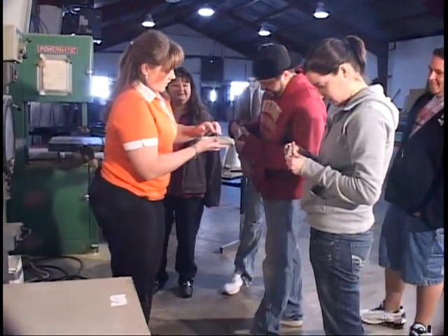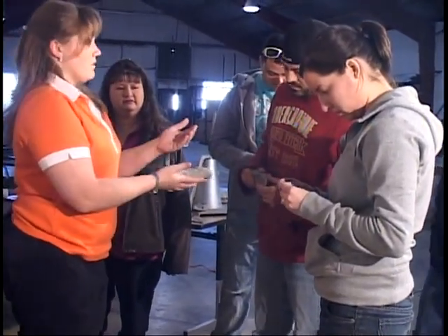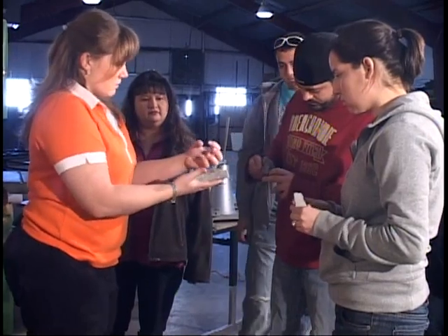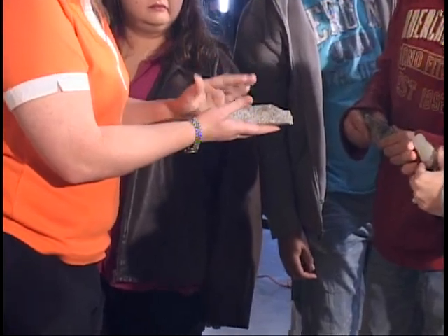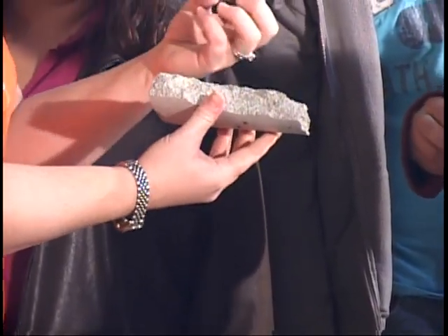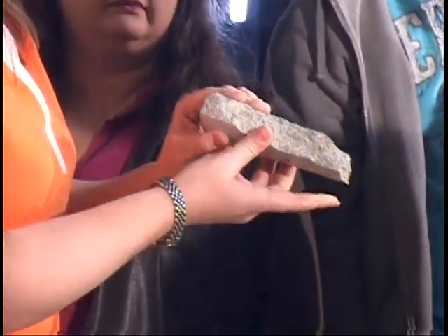And it can break around the pieces of sand and break around the aggregate. Sometimes it breaks through the aggregate, but usually it's the bond between the paste of the cement and the little pieces of aggregate in it. And if that bond is strong enough, that's what gives the concrete its strength. So you put larger aggregate in, as long as it's bonded the paste to the aggregate, it should give it more strength. Okay.